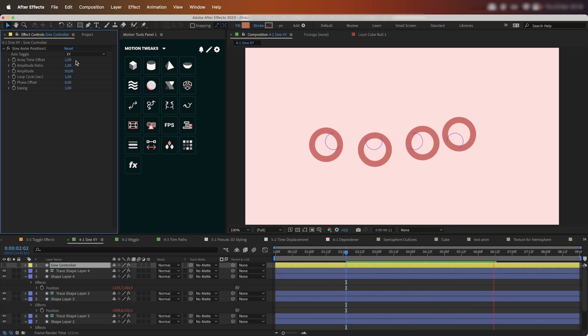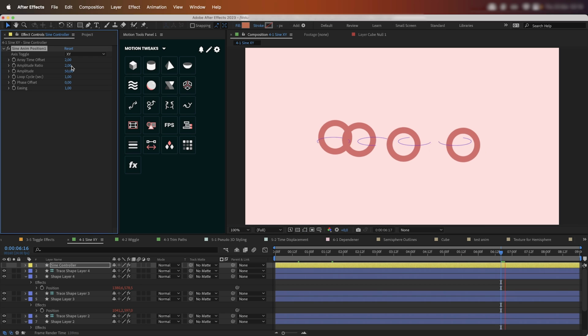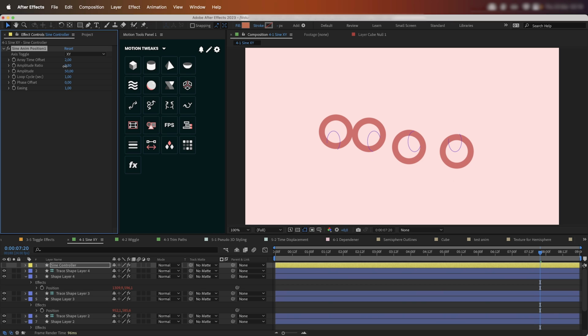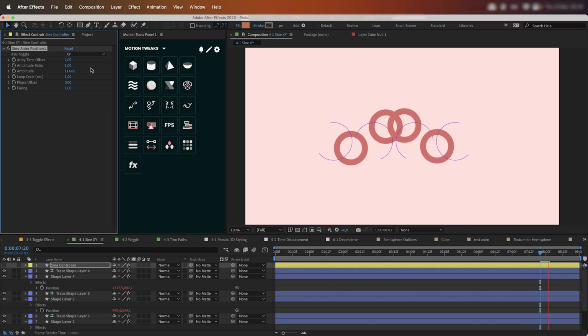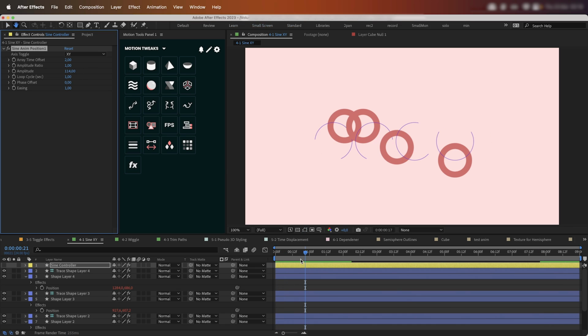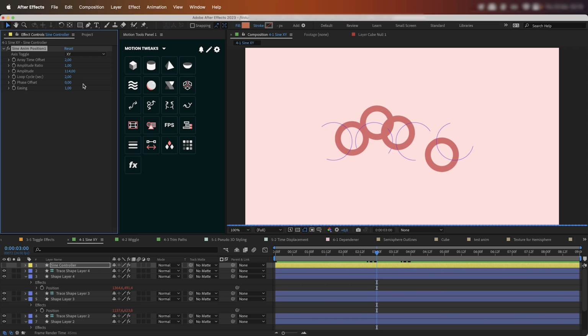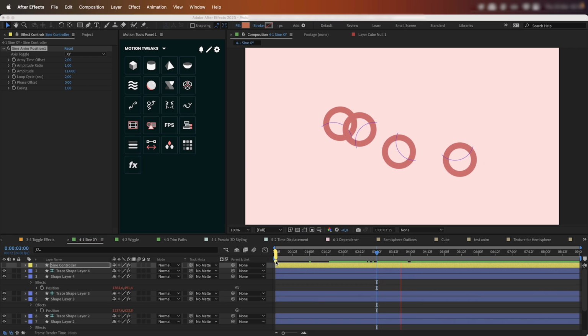Amplitude ratio allows you to simultaneously decrease and increase the amplitude of each axis, so the movement trajectory has become more oval. Amplitude increases the distance traveled. Loop cycle controls the animation speed. By default, it is set to 1. That is, a complete looped movement will take 1 second. By setting it to 2, I'll increase the cycle to 2 seconds, thus slowing down the animation.